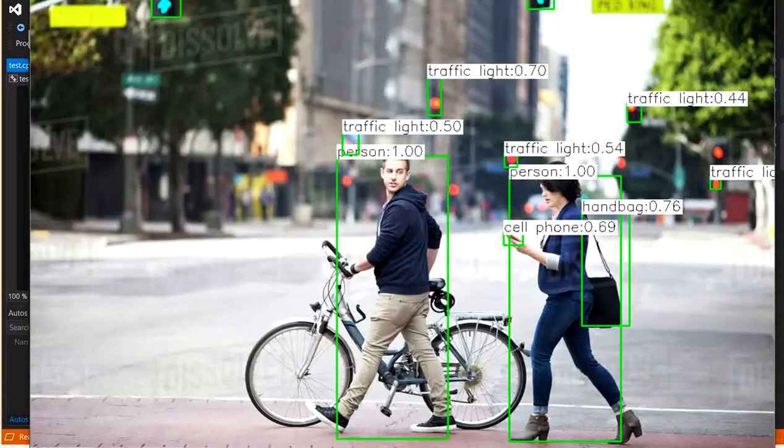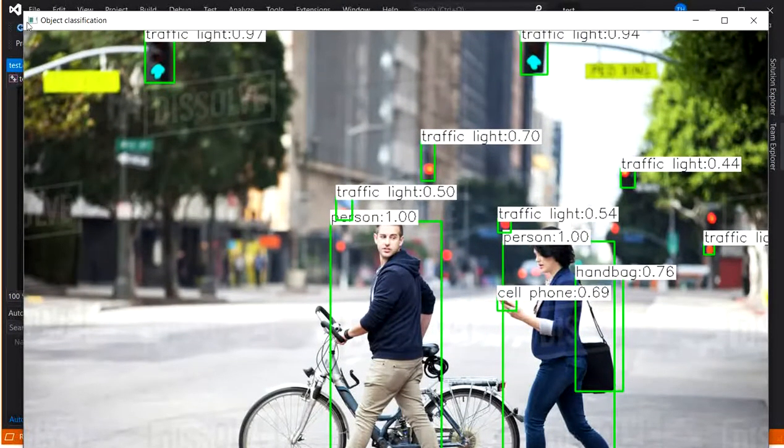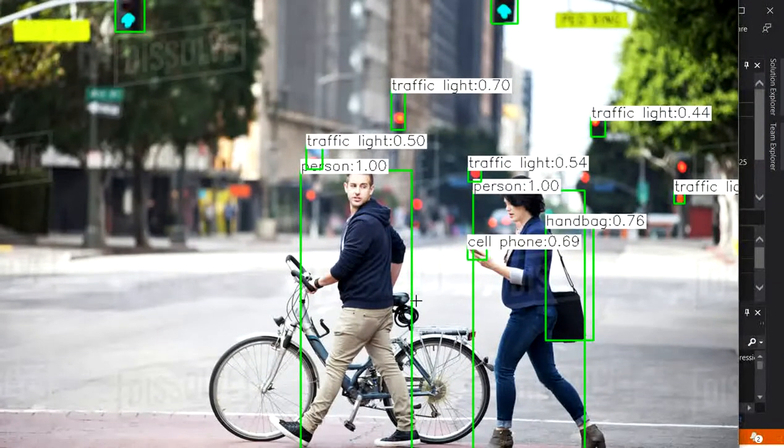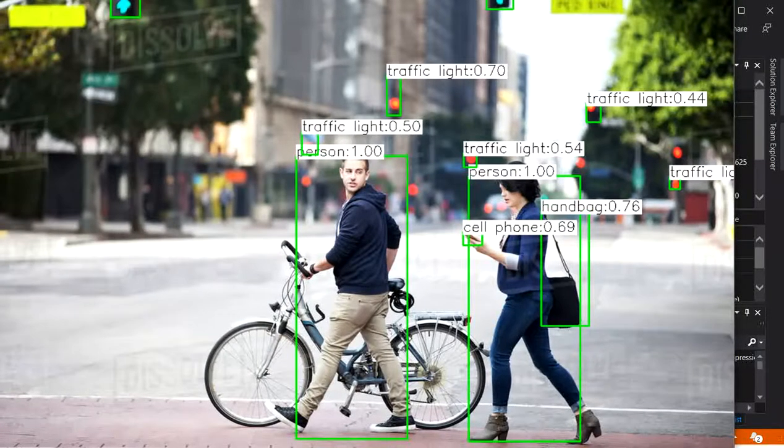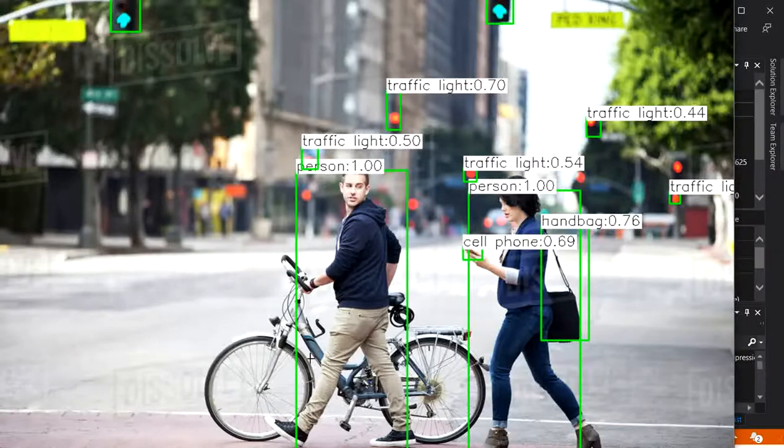And it can detect the traffic and the people right here. It can detect the person. So from this, our purpose is to create bounding boxes of the objects right here. And after that, we fuse the lidar point data into this region. And after that last step, we calculate the time to collision to the object in front of the camera.